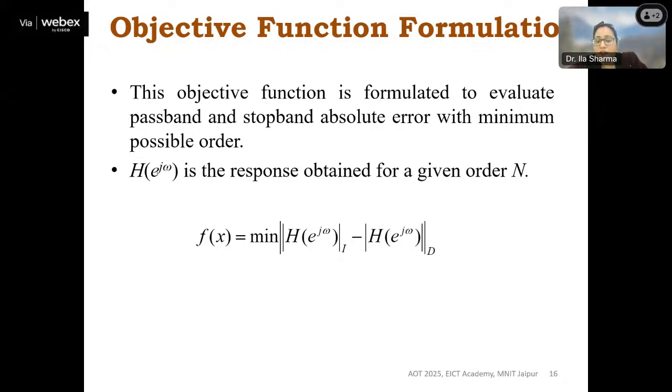Let's suppose whatever filter you have designed, by any of the approaches, the classical, the windowing, whatever it may be, it is not giving the constant value throughout the passband region. So it is giving fluctuation. Its value would be like 0.98, 0.96, 0.97. So basically it is not 1 but something other than that. So we are computing this error value over all the passband region. Ideally we are computing 1 minus all the calculated design filter magnitude responses, and we want to minimize it as much as possible.